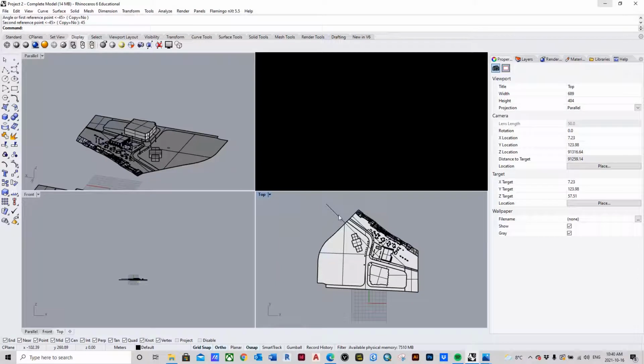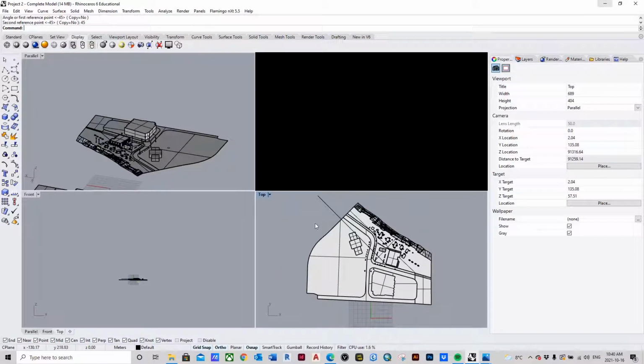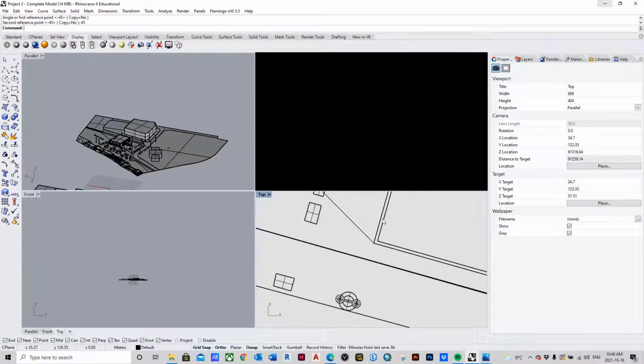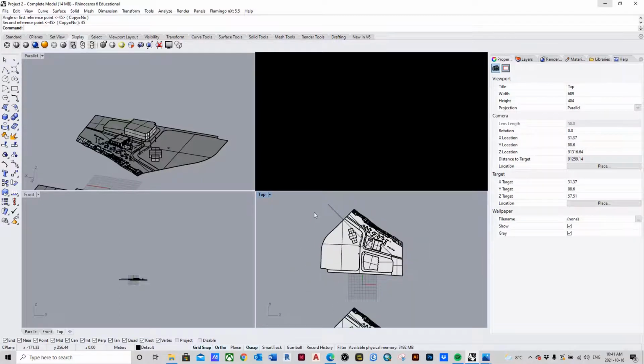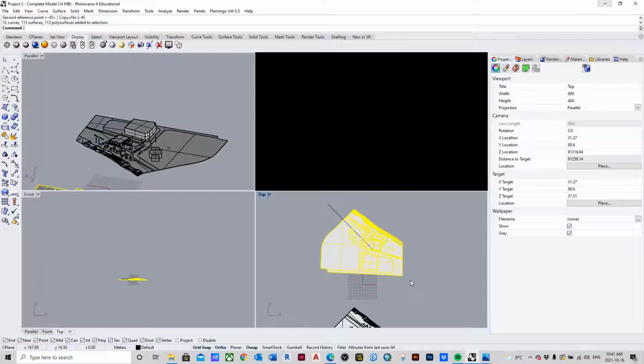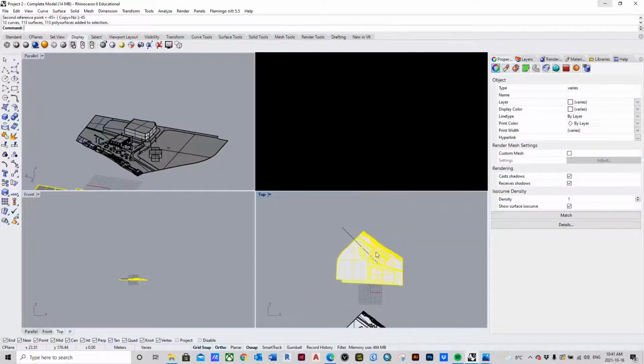Now we're going to use the rotate tool again, and we're essentially going to rotate it so that this face here is concurrent with this ruler line that we just made for ourselves. So here's how we're going to do it. We're going to left click, hold down. We're going to drag, holding. We're going to move over the entire model, release. Now that whole thing is selected, but this part isn't, because we don't want that bit to turn. That's just our ruler here.